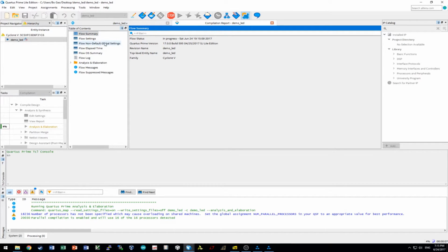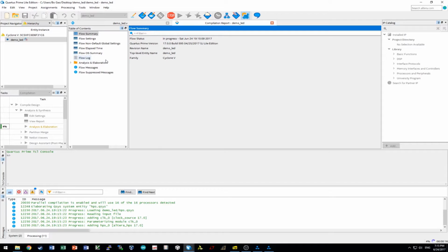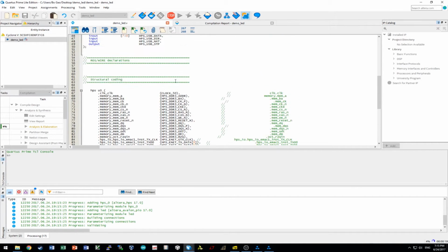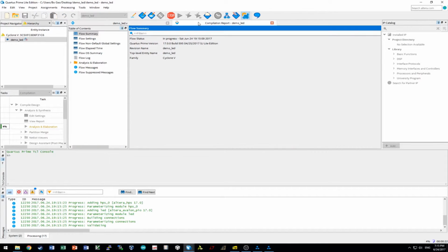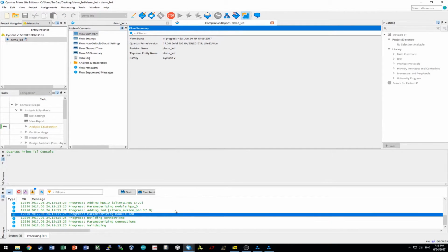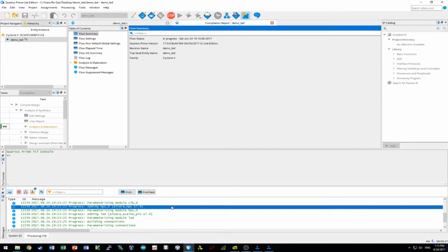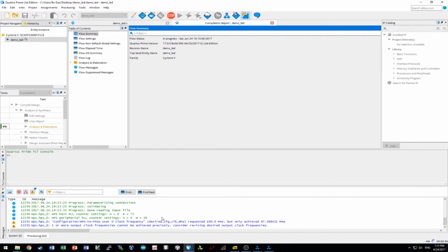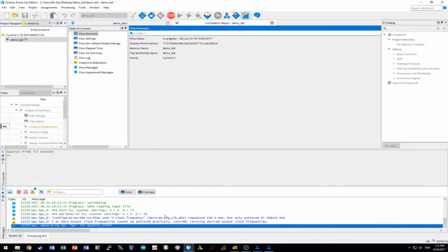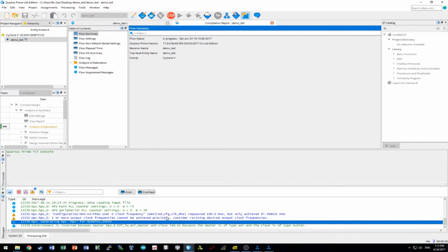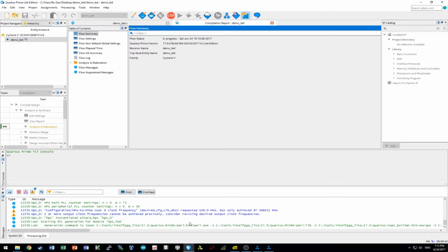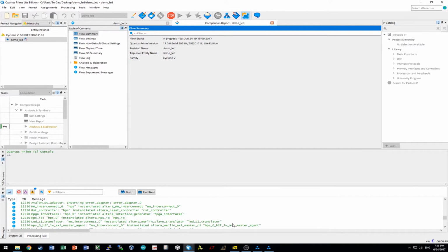This should be fairly fast compared to full synthesis. So the goal is to let Quartus know the I/O port declared and assignment. So now it knows we have the HPS module, it knows we have all the pin setups. That's good. See that interconnection inserted between the AXI bus and the Avalon bus. There's a bus translator, correct? These are all Qsys's job.